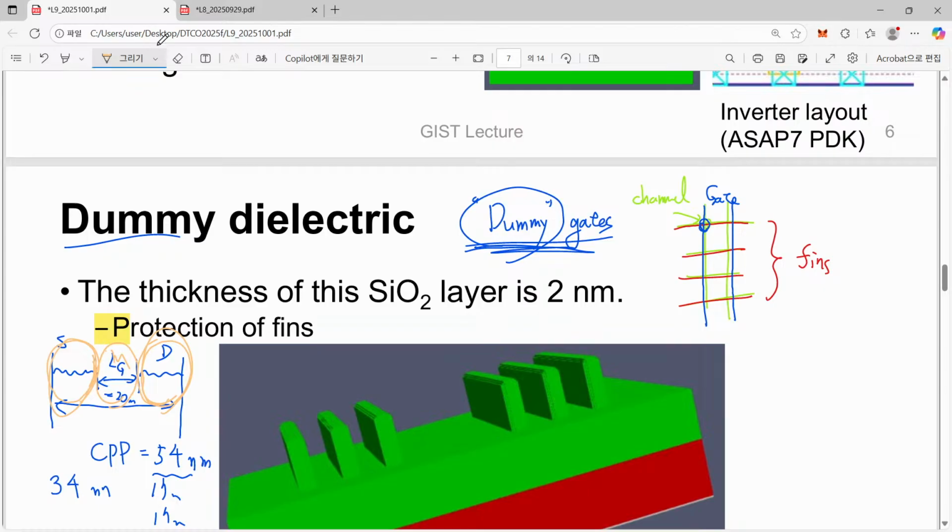So simply speaking, in this structure, even this short 17 nanometer should be divided, and our source has just a portion of this 17 nanometer, and in between them we have to introduce a certain intermediate layer to separate source and gate, and also separate drain and gate. These are required, so it is quite tight. Okay.